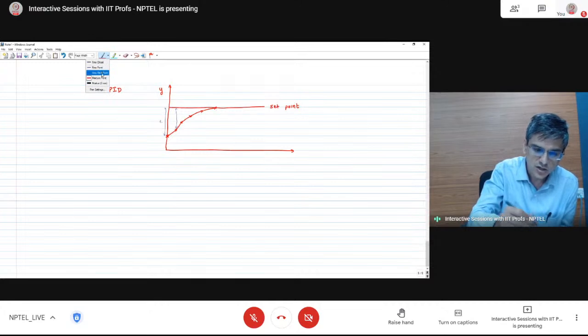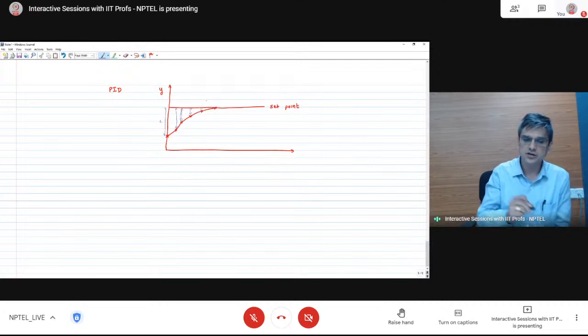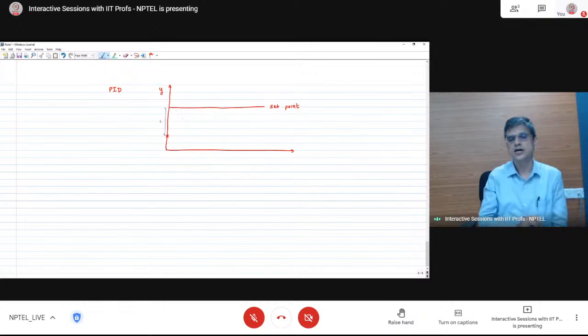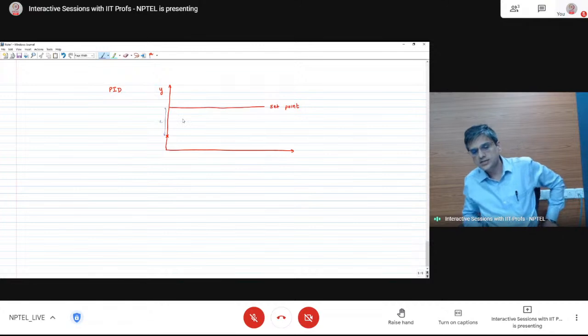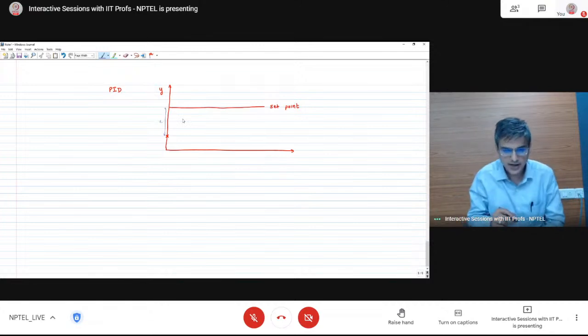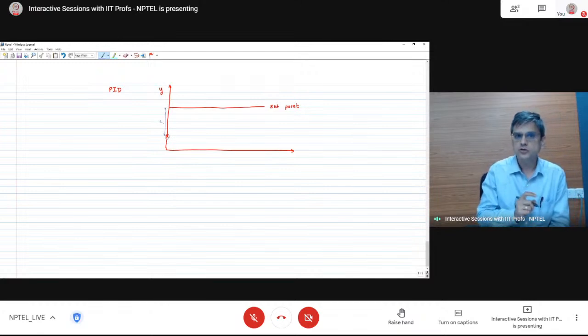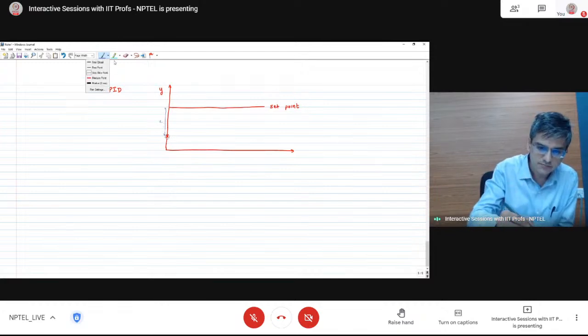So a PI controller, at every time instance, is only taking in the outputs, comparing them with our set point, and determining what is going to be our next control action. What does MPC do? At this point, MPC is not at all going to look at the error. It does not look at this error at all.